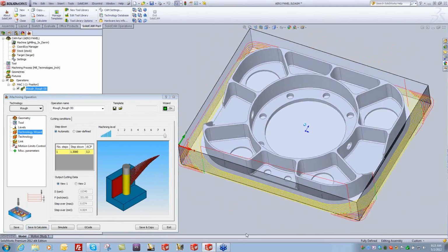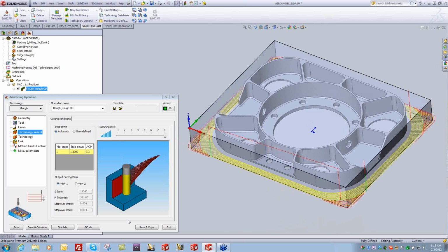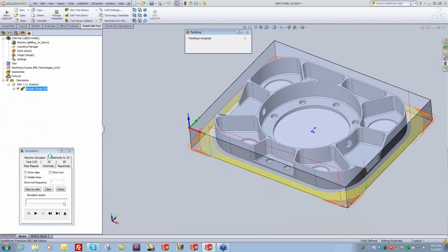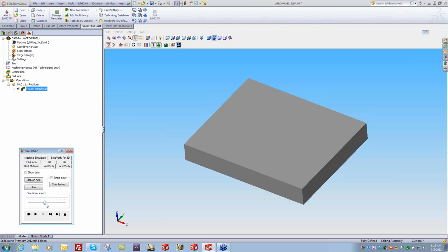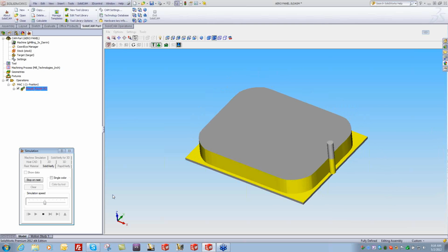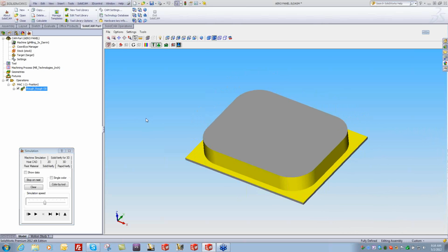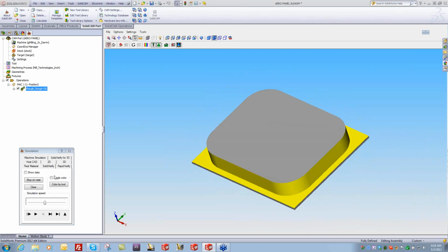That is an iMachining toolpath that looks quite a bit different than a standard traditional toolpath. Let's go into simulation real quick, into Solid Verify, and we'll take a look at how this will cut. Always managing the tool's engagement. It's going to take off the material where it needs to first so that it can get into more of a race tracking style, which is basically a spiral toolpath. That's what you're looking for. Now, if we turn on our show data, we can find out how long that took to run. 1 minute, 21 seconds. Real close to that, give or take a second or two.